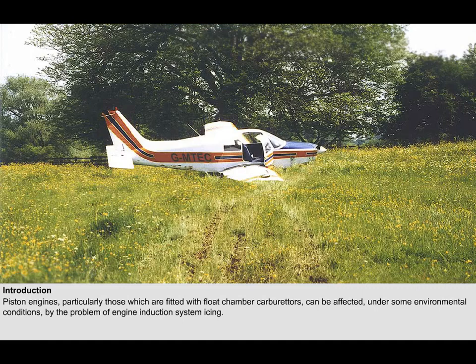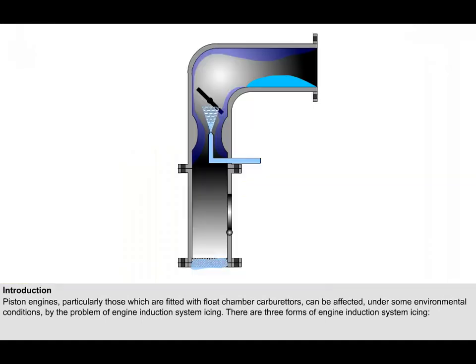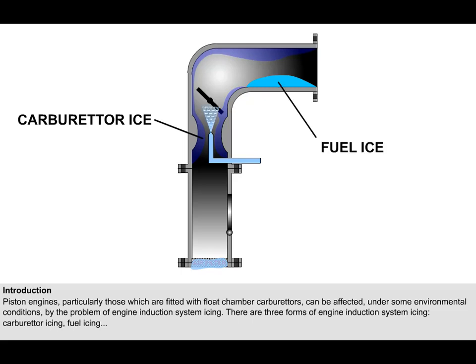Piston engines, particularly those which are fitted with float chamber carburetors, can be affected under some environmental conditions by the problem of engine induction system icing. There are three forms of engine induction system icing. They are carburetor icing, fuel icing, and intake or impact icing.